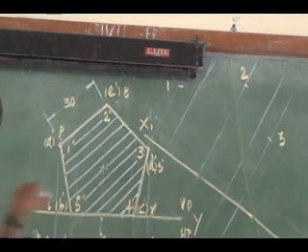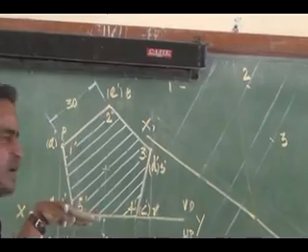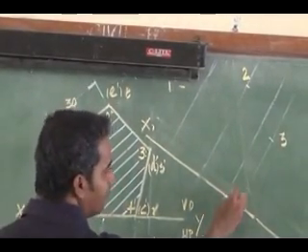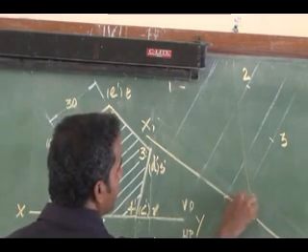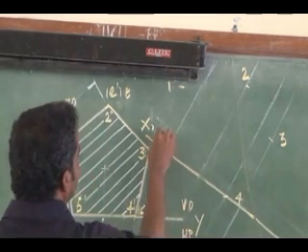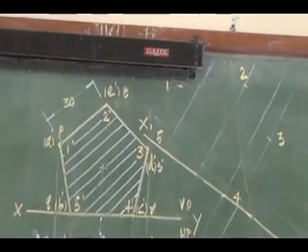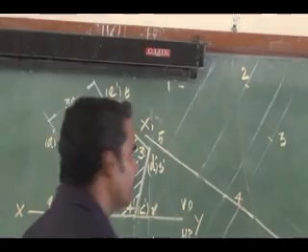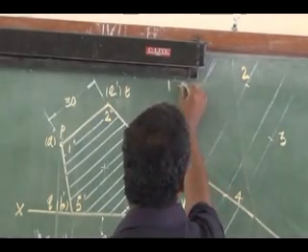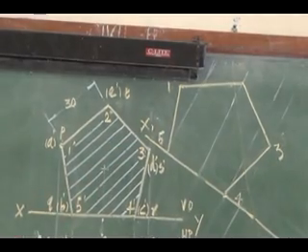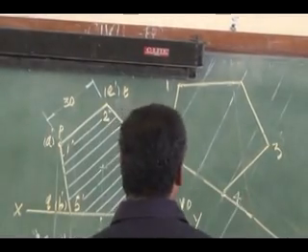Cutting point 4 falls on the old reference line, so from the new reference line, again it falls here. That is my cutting point 4. Here is my cutting point 5. Right. So just by connecting these cutting points in sequence, this is my true shape of section. Just you can ask that.